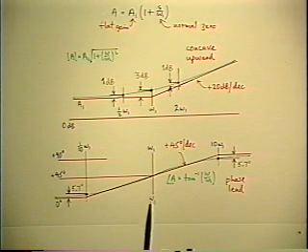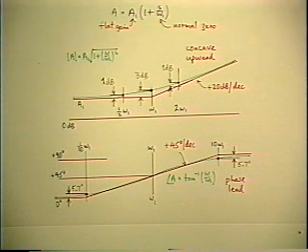That's a useful thing to know, because what it tells you is that the phase is a more sensitive indicator of the presence of a nearby corner frequency than is the magnitude. And it also tells you directly that if you have a corner frequency, its influence is going to extend further away in the phase graph than in the magnitude graph, and that's an important thing to know when we start talking about stability of feedback systems, where the phase margin is one of the important design criteria.